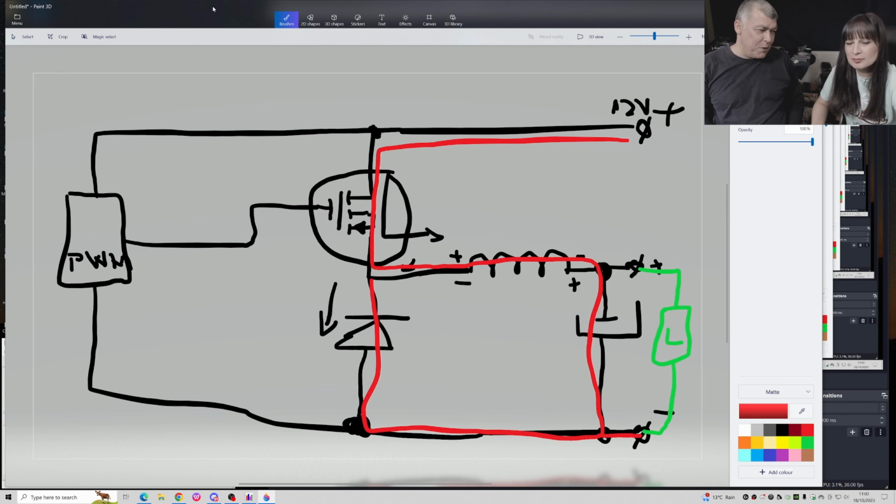Now there is another confusion. People are confused a lot about this power supply. They said, okay, we have this power supply, and we set up the duty cycle and we have 5 volts on the output, right? Now, if you have 5 volts on the output, this capacitor has 5 volts. It's not like ground. Because what we spoke until now, we said this capacitor is like a 0 ohms resistor. Now, if you have 0 ohms, it's the same as having the ground here. But if we have 5 volts, this is not like 0 ohms. This is a confusion.